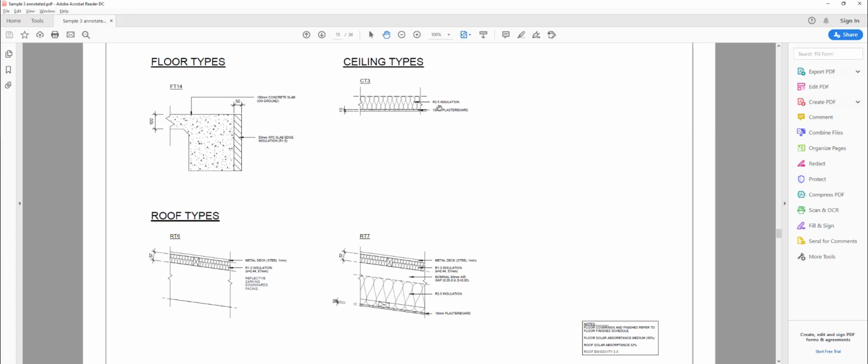The metal deck roofing with an R1.3 insulation blanket, reflective sarking facing down, is going to be our main assembly here. So it's a metal roof in a roof space, and it's got R2.5 ceiling insulation, R1.5 roof insulation, reflective down. Our pitched roof section is a very similar construction, but with that ceiling on a pitch, R2.5 10mm plaster, and again a reflective airspace.